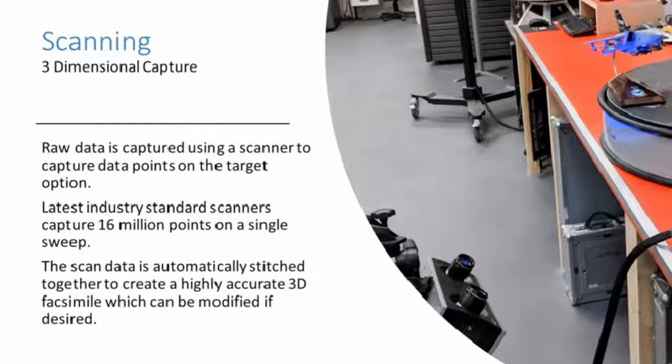3D scanning is one of the two main inputs for capturing data which can then be manipulated as required and used as the basis of the physical ALM output. 3D scanning is a fast, efficient process used to collect 3D point cloud data for the creation of three-dimensional models. Each of the millions of data points that make up a single composite scan has its position accurately rendered in 3D XYZ coordinates, meaning that positional data and details from the scan object are captured with great accuracy.